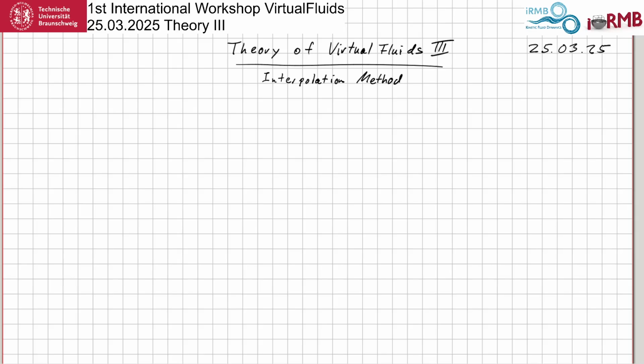So this was on the schedule, and the reason for this is that the lattice Boltzmann methods, not all of them, but the one that we have in VirtualFluids, is a completely Cartesian grid method, which is not good for all possible applications. So two problems, and the two problems we're going to discuss is that boundaries are usually, or very often, not coincident with grid points. So you need to deal with off-lattice or off-grid boundary conditions, so cut cell boundaries.